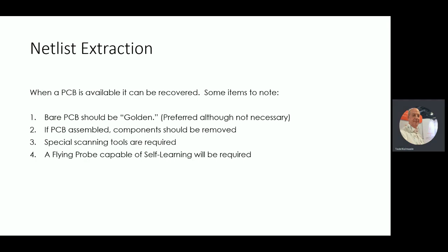And so then after that, we do a process of testing against that netlist to make sure that it will pass to what it learned. And if it didn't, we do some investigation. If it missed a pad or if there's some solder mask in the way, all these little things can come into play.